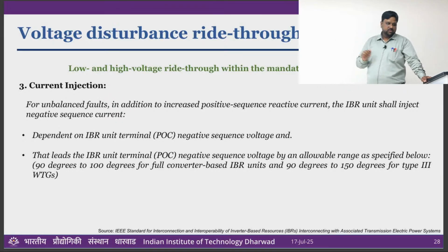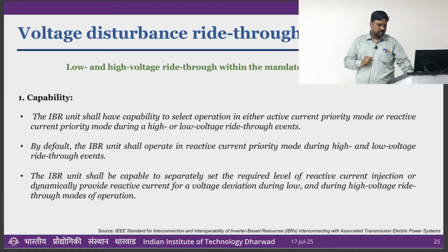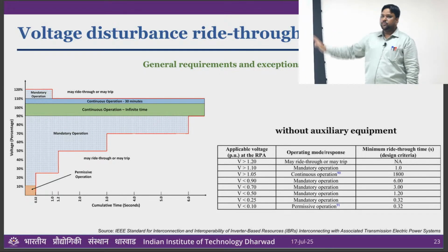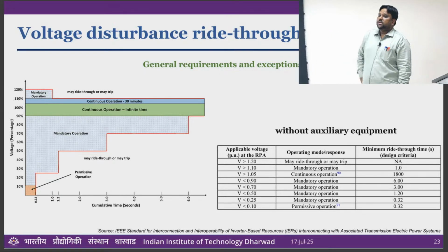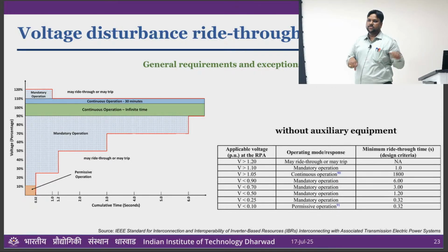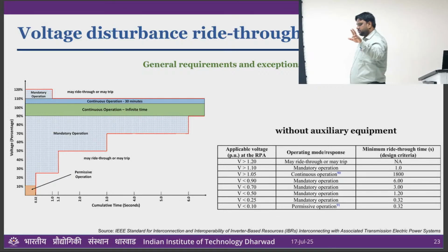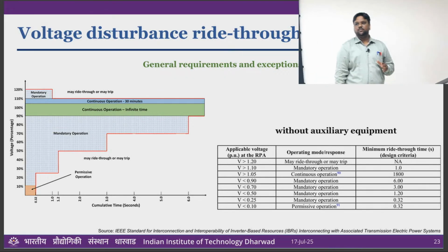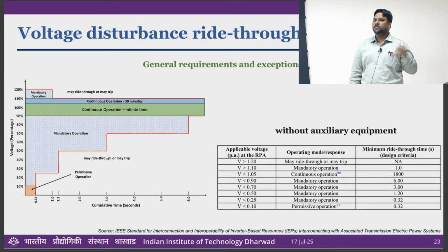But the important catch is here. This curve I showed, let's say my voltage falls to 40% at the POI. But do you think the inverter will see 40%? No, it will not, sir. Because you have lines and transformers, all of which have to be added up. Then whatever your inverters see, that is a big research topic, or some kind of discussion going on, because we are facing an issue in the Rajasthan